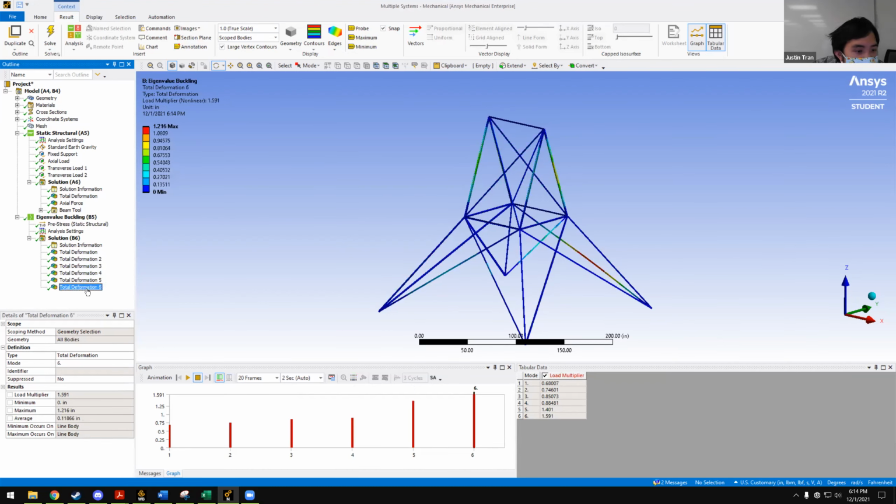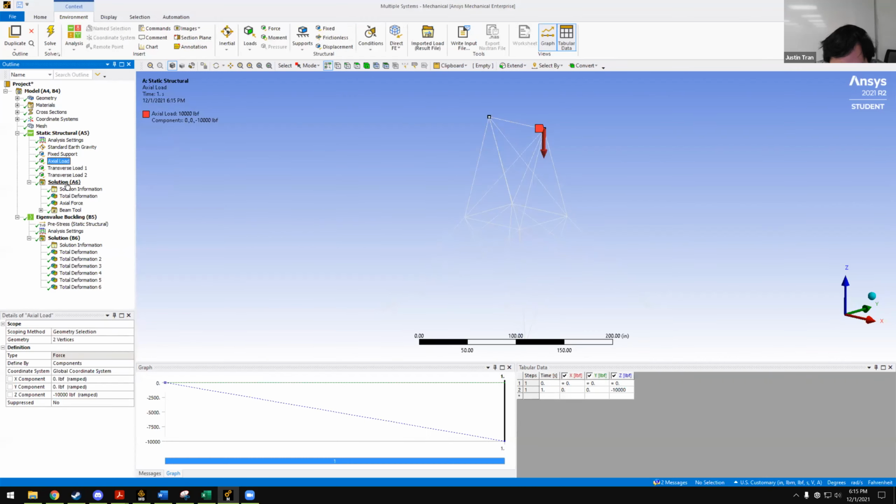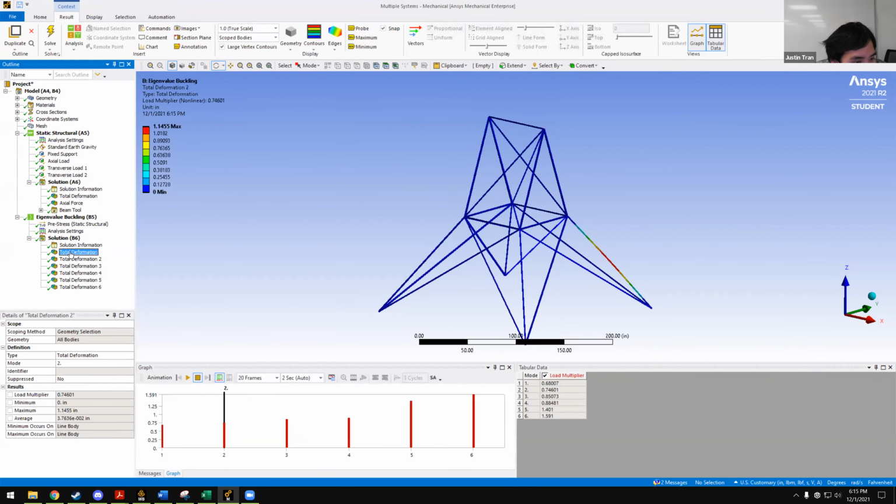Yeah. So what you're viewing here for the six, those are just the shapes of the buckling modes, and so we haven't actually applied those multipliers onto the structure, right? Oh, your multipliers are less than 1. Oh, that's interesting. And so when I say to apply the buckling multiplier, what I mean is let's take the first mode. And so the first mode was 0.68, right? So do you see that in the bottom right of the screen?